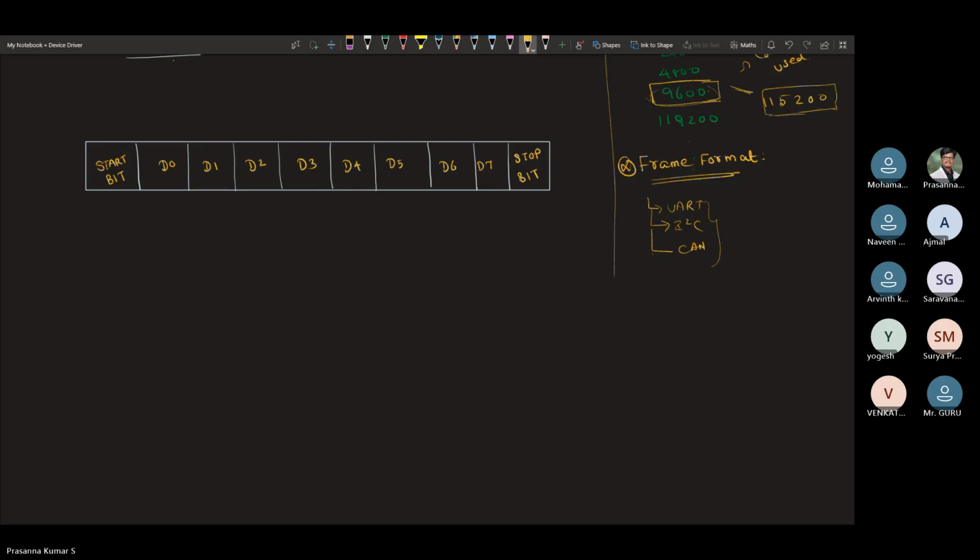So this is the start bit and stop bit, and we call this the data frame. We are going to transfer 8 bits of data in the UART. After this, the next start bit will come and all these things will happen. Now, how we are going to define the start bit and stop bit: all these things are pulses only.